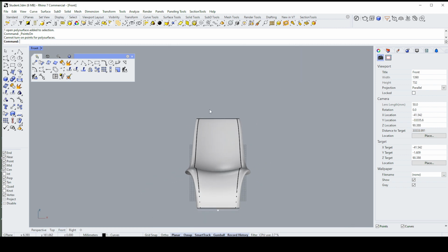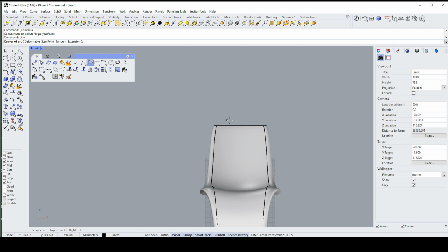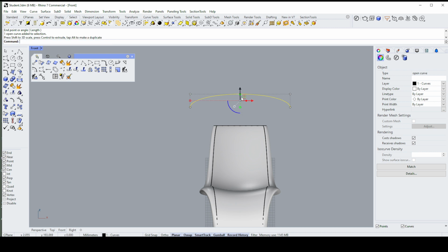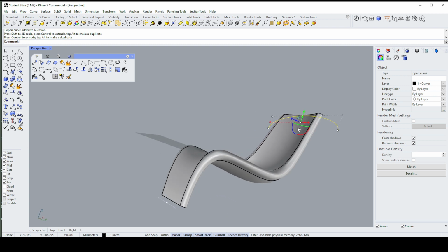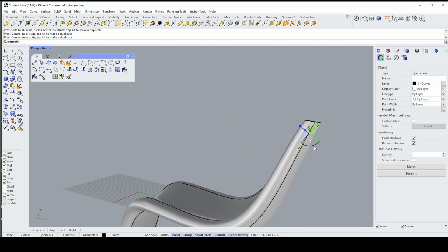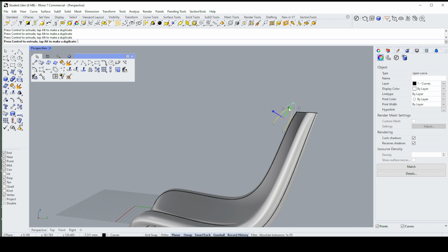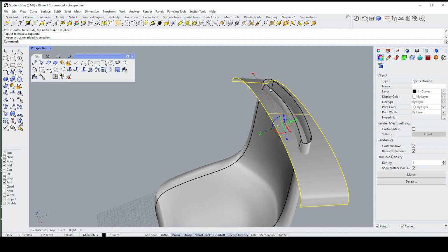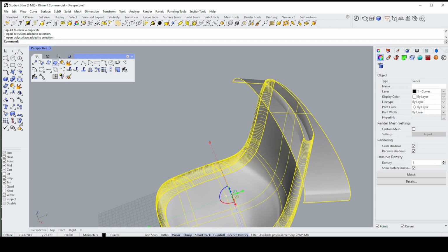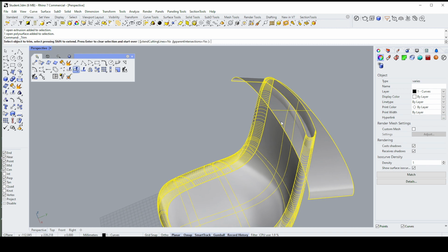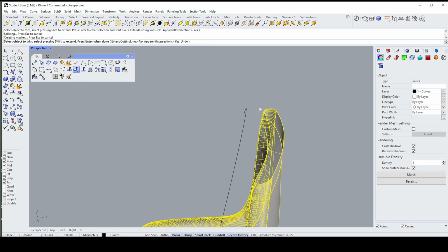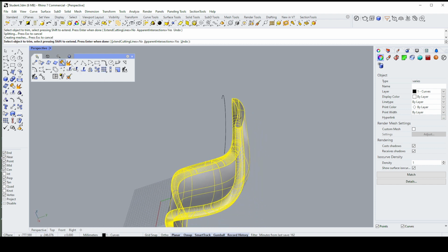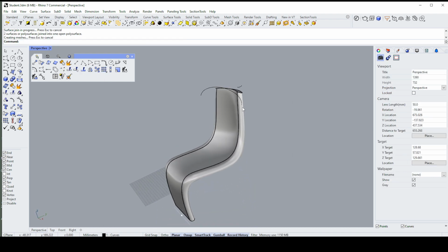Let's do one other thing. Let's do something like this. All right, I want to chop the top of that off. Let's just rotate this, come down a bit, extrude it, and then I'm going to use that surface to chop this one off, and this one to chop that one off, so that we've got a cap. So we'll go to trim, and trim that one, and then I'm going to join them. And so I can do the same at the bottom, but here we go.